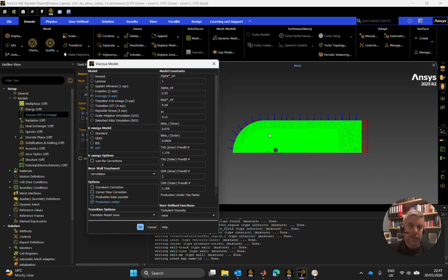Each aerofoil will, I suppose, pull out certain characteristics of the flow field for a given velocity. So yeah, Spalart-Allmaras is fine if you're 100% sure of how the fluid flow is going to interact with the surface. If you don't know, k-omega is not bad.